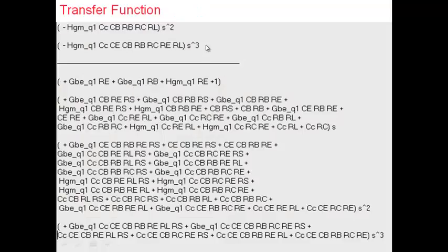So note that I have the transfer function. I have a constant term, then an S term, an S squared, and an S cubed. If you have the transfer function available, in principle, what can you do? You can plot it out and find out where the function drops by 3 dB. Except that I don't think I can get an expression for 3 dB from here. I can take this function and plot it numerically and find the 3 dB point, but I don't think I can get an expression from here.